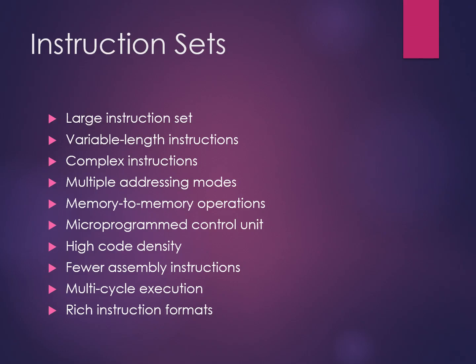So what are some of the instruction set characteristics? There are large instruction sets, variable length instructions, complex instructions, multiple addressing modes, memory to memory operations. Again, micro-programmed control unit, high code density, fewer assembly instructions, multi-cycle execution, rich instruction formats. All these are the characteristics of CISC instruction sets.